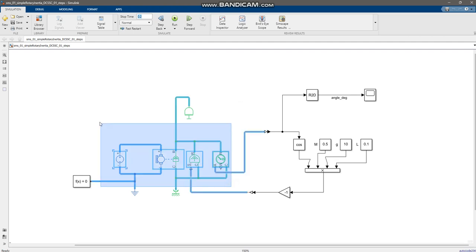If it were not for Simscape, if we were developing the motor side and the inertia side using Simulink blocks, then we would have had to compile another set of equations to model the torque of the stepper motor and implement them using Simulink blocks, change the connections between those blocks and implement the final effects through an ideal torque sensor. So that would have been quite a tedious task.